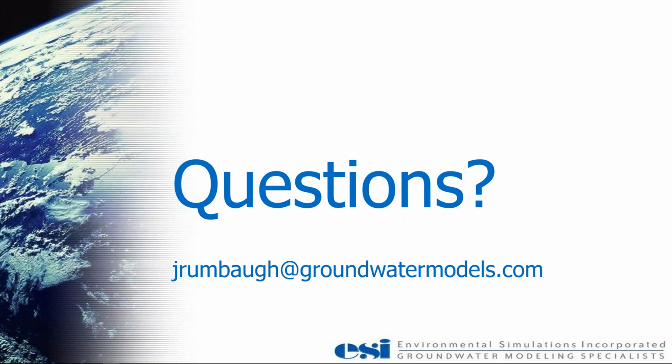Another question is, is there a version of zone budget for MODFLOW 6? Yes. Well, I guess there's two parts to this question. Groundwater Vistas does mass balance just like zone budget internally, and it works just like all the other versions of MODFLOW. So yes. But the USGS also does have a new version of zone budget to work with MODFLOW 6. Groundwater Vistas just doesn't use that. So you're welcome to use it if you want, but we have not implemented any connection to it.